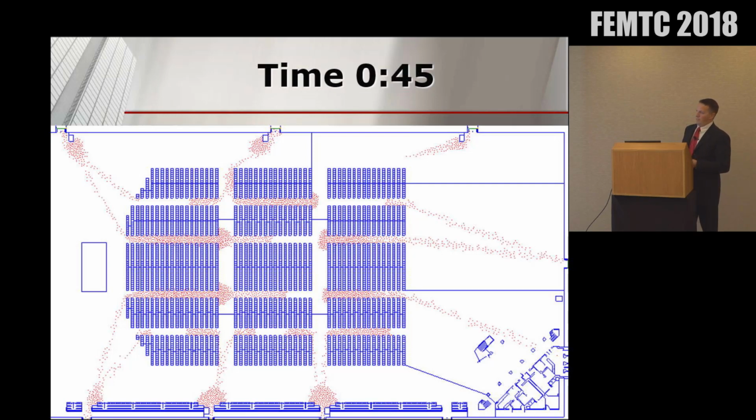Something that's struck me was how we start to see queues forming around obstructions, and then just a thin stream of occupants coming through. There's been studies in Japan that talk about if you have a barrier near an exit, it will reduce conflicts and improve efficiency. But in Simulex, it's a barrier to the most direct path, and so we don't gain the efficiencies that those researchers saw. It results in inefficiencies.